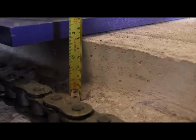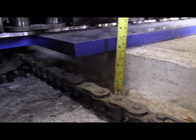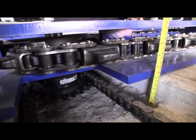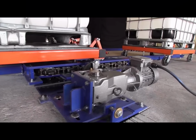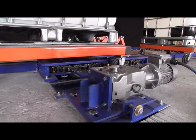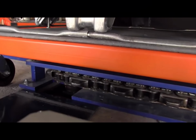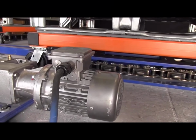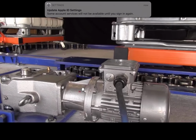First is the extraordinarily shallow trench required to install a drive unit. A 2.5-inch recess cut into the floor is all that is required for this drive unit. There is no in-floor pit. There is no major floor work required to implement this tow line. It is also an easy cutaway to repair should the entire system need to be relocated to a new facility. It's easy to install, it's easy to use, and it's easy to move. The above-floor motor drive is also easy to service because of its accessibility.